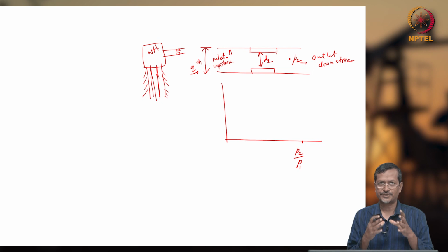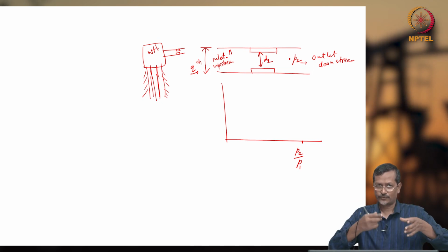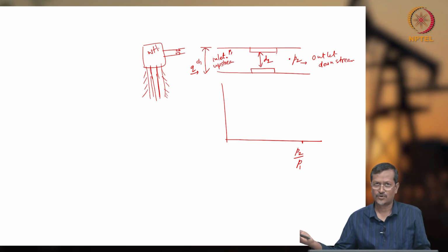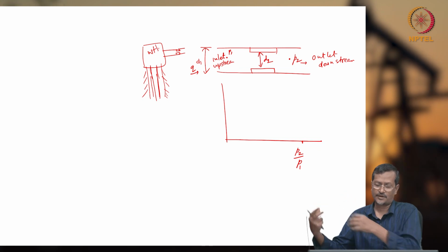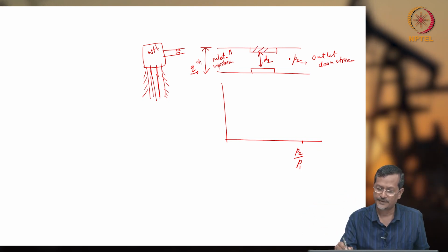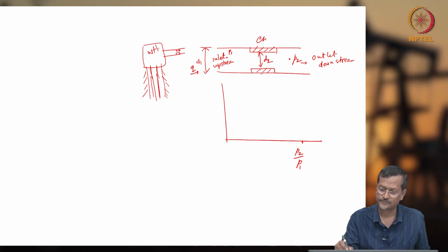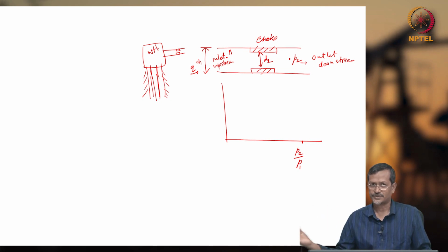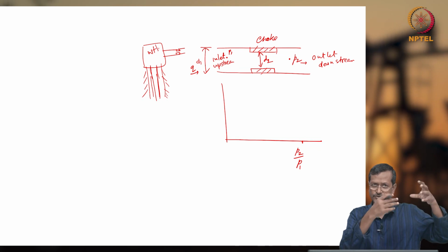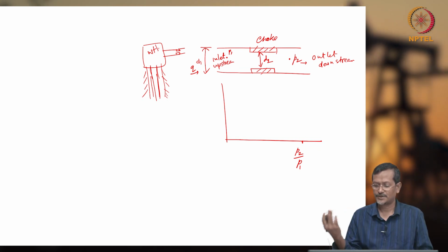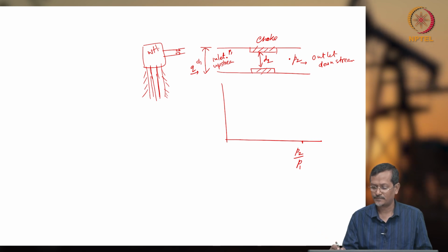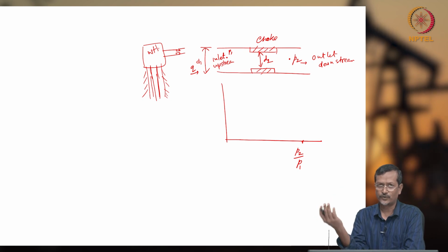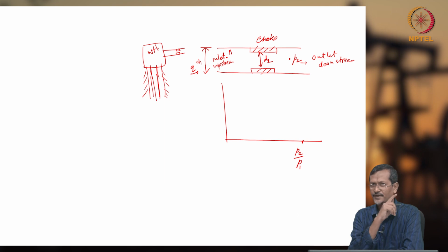because wellbore pressure is fixed, wellhead pressure is fixed, so whatever the wellbore is delivering, that upstream pressure may be 1000 bar or 100 bar. Now, downstream pressure you can actually control. Let's say you can put a very big restriction after the choke, right? This is the choke. So after the choke, you can control the pressure, but upstream pressure you are not controlling, because it is controlled by your reservoir system. Now let's say initially downstream pressure P2 becomes 0, very low pressure. When P2 is very low and P1 is very high, at that time you will get a very high flow rate.